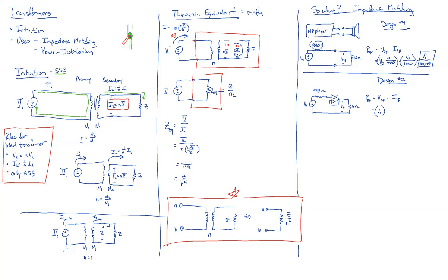Because there's no current, current can't flow into an op amp. So this 990 ohm resistor drops nothing. And so the Thevenin equivalent to the left of the output of the buffer looks just like a pure voltage source. That's the benefit of the buffer. It just removes the Thevenin equivalent impedance entirely. Okay, that makes more sense.